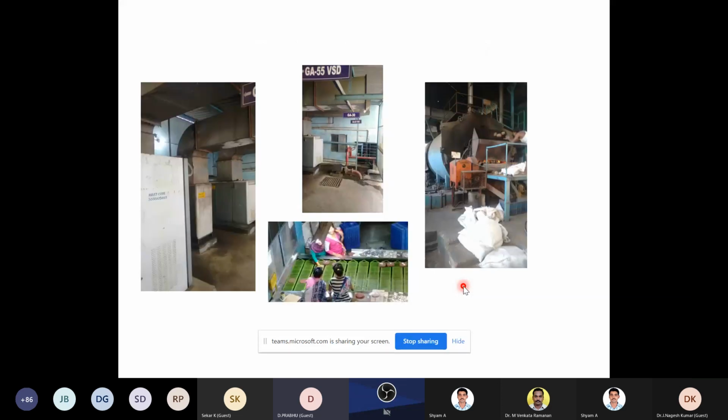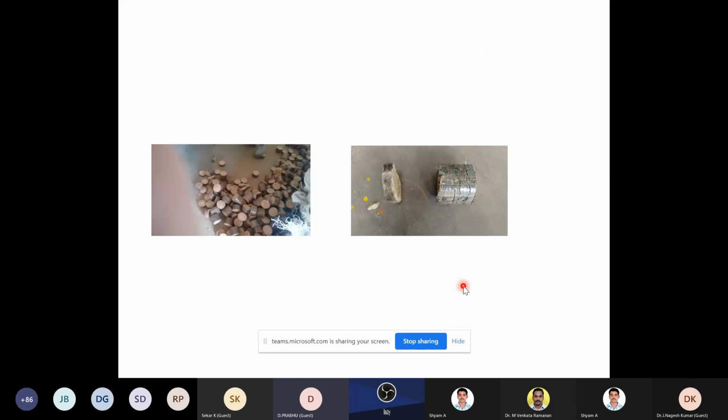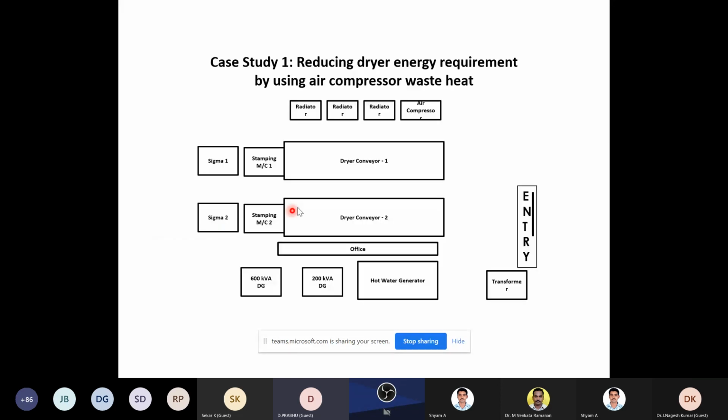See, one of the simplest things here, this is a hot water boiler. Instead of steam, they're using pressurized hot water. This is something which is there in the industry. Say, for a dryer, for example, this is a mosquito coil manufacturing plant. The mosquito coils are stamped, the shapes are made, and then they are put on a drying conveyor. That's all, a simple process. This dryer has to remove the moisture, so the dryer temperature is made at 80 degrees. For 80 degrees, we don't need steam.